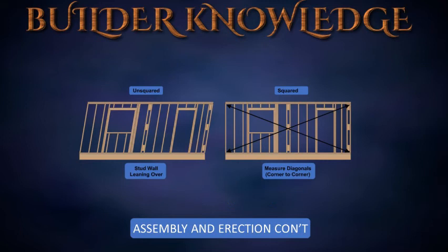Square the framed wall. Position the wall so that the bottom plate is next to the chalk line that shows where the wall will be fastened. Tack a few blocks at one side of the line. Push the wall against the blocks, and at each block, tack the bottom plate to the subfloor. Using two tape measures, measure diagonally across opposite corners. When the two measurements are equal, the wall is square.